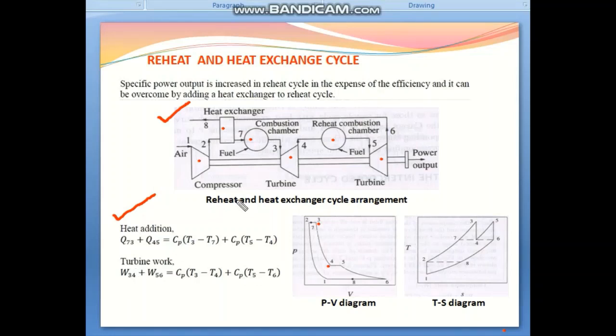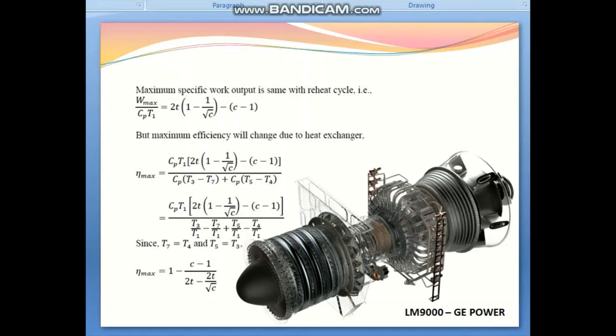Turbine work, this system has two turbines, turbine 1 and this one is turbine 2. So W3-4 plus W5-6, that is equal to Cp(T3 minus T4) plus Cp(T5 minus T6). Okay, this is the turbine work. Now the maximum specific work output is the same as the reheat cycle, that is Wmax by Cp T1 equals 2 into (√τ minus 1)...